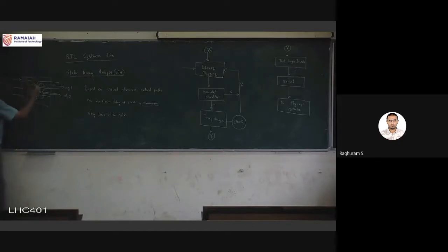So this is one path, this is another path, like that. In this diagram, I don't have any other colored chalk, but if you see closely, there are four paths. Which of these is the critical path? The paths will be identified by the static timing analysis tool, and it also has to identify which is the critical path. That is the easy task.